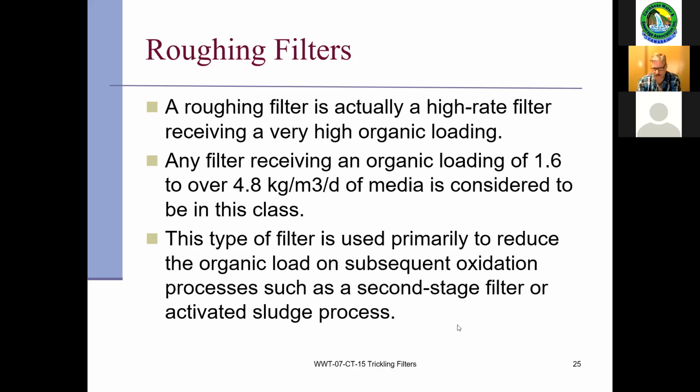So maybe in a fruit industry or some other kind of industry that needed to shave off that organic load before it went into the wastewater system, you could have a trickling filter in there. The roughing filter is just hitting the peak of that treatment, so you can then discharge it to a sewer system.